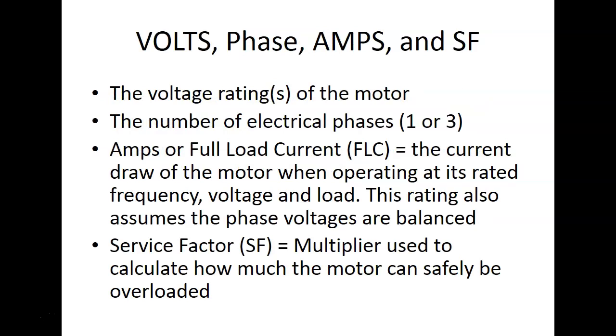So y'all get up and go to y'all's workstations. Y'all look at y'all's motors and see what's on these. So the motor, what's the amps rating? Okay, great, guys. What's the amps rated on the motor? At rated voltage, right? Rated load and rated frequency, right? You understand that? What's the service factor?